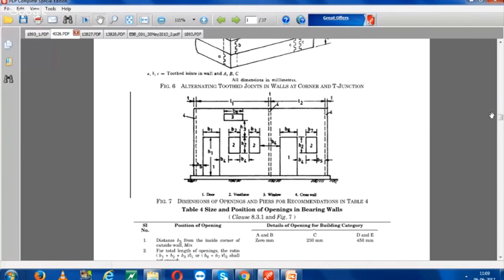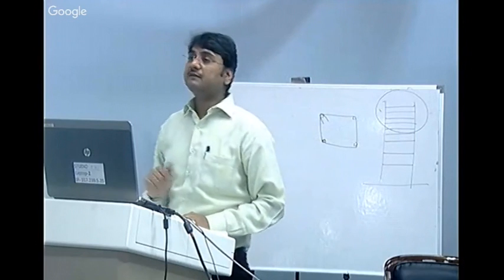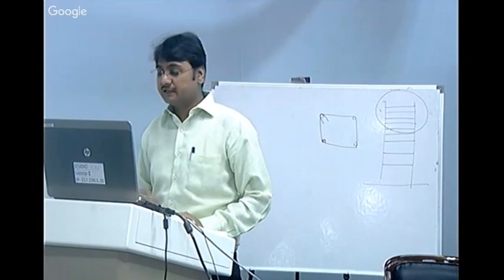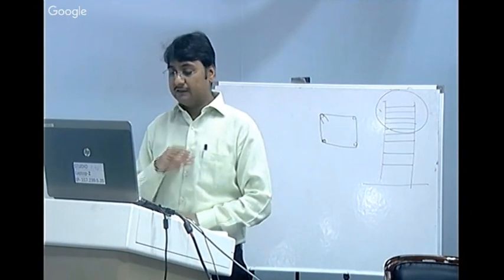That weak link is not a structural member. Whenever my building rocks in the earthquake, all the stresses will be taken by that weak link, and that weak link will be ruptured or yielded without damaging the structure. So that is called the ductile mode of behavior of the structure. That's why here we keep the stirrups closer to the joints, so that whenever more forces are concentrated near the joints, a ductile kind of behavior will be there. So this is how you can answer that question.